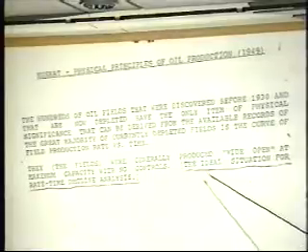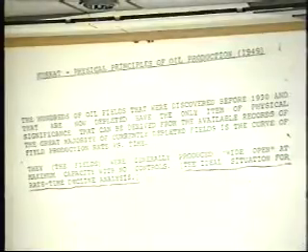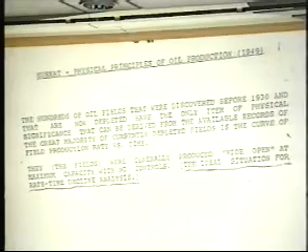And this is my underlining in brackets. This is the ideal situation for rate time decline. So we can go back and look at a lot of these old fields, their performance behavior, and these were the types of fields that Cutler and Arps, you'd taken that data, and that's how they came up with the empirical, or at least Arps came up with the empirical rate time decline, based on field data.